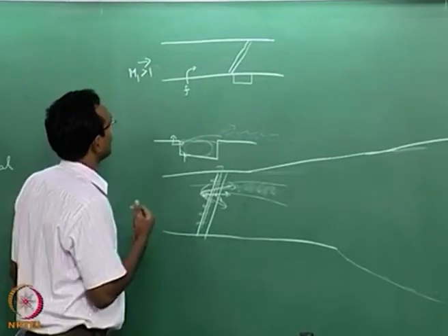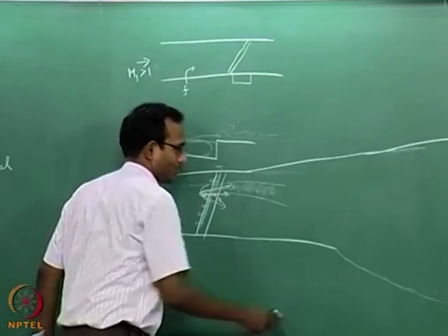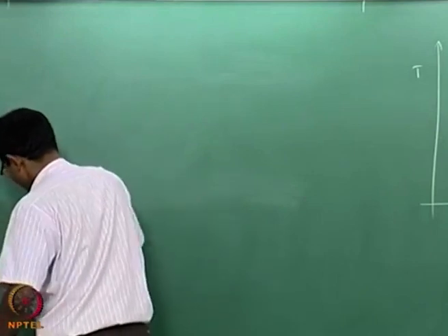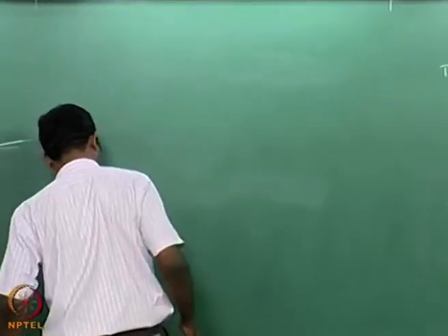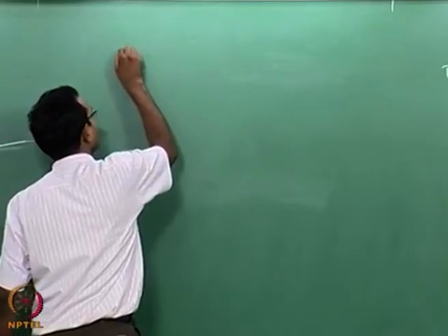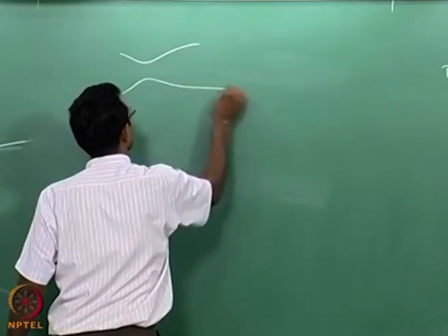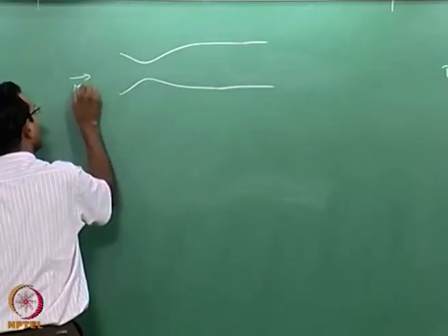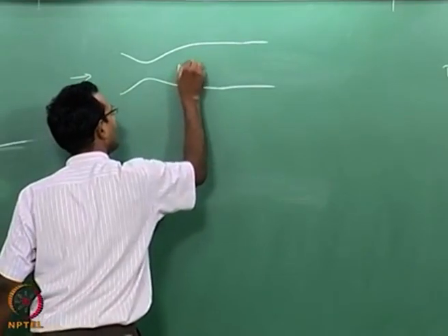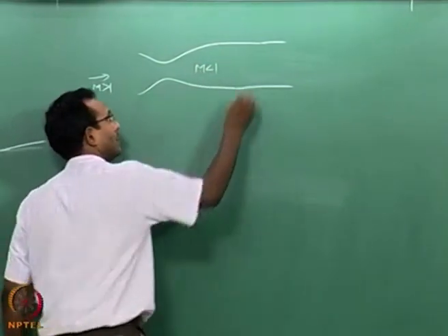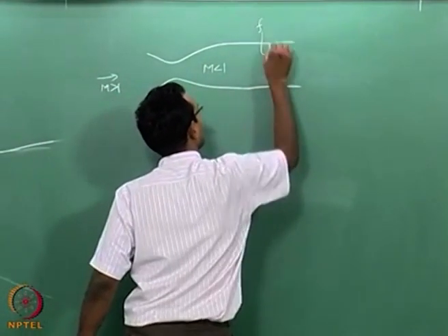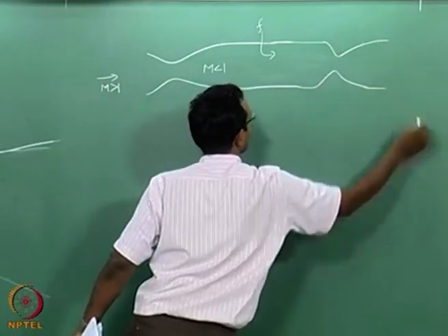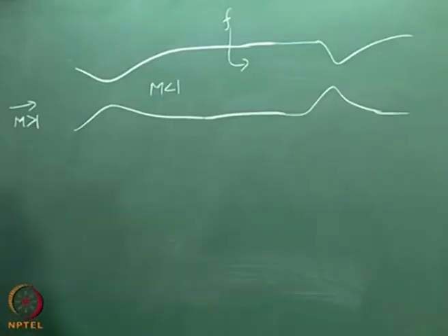If I think about a subsonic combustion but a supersonic vehicle, a simple ramjet. Just a ramjet. I am flying supersonic, but near the combustor it is subsonic. How do I do it? Typically there will be, and this is where I am going to add fuel and burn inside. Then I will have another nozzle to create thrust further. This is going to be my system.